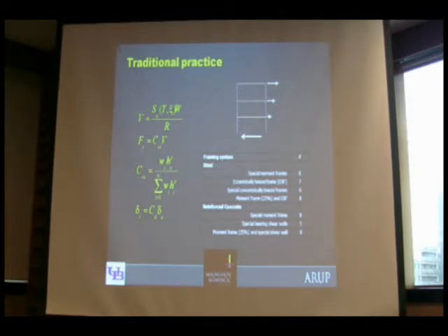Then we take these reduced elastic forces, impose them on an elastic model of our building frame, and go ahead and design our structure. We assume that this process leads to a structure that's able to deliver life safety in the design shaking consistent with this spectral acceleration. It's an unproven and potentially unreliable process. But this is traditional practice.